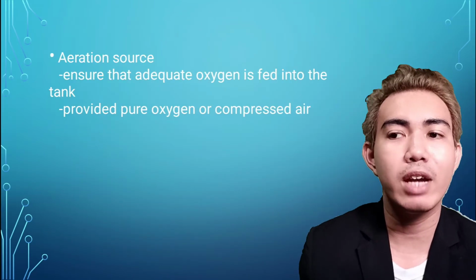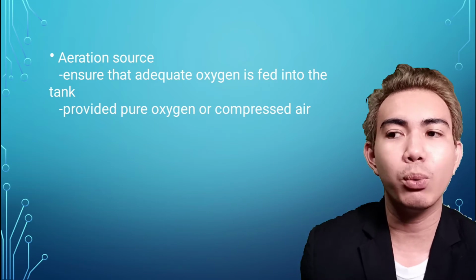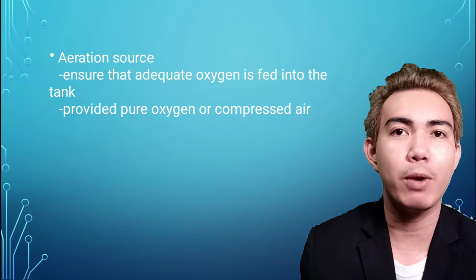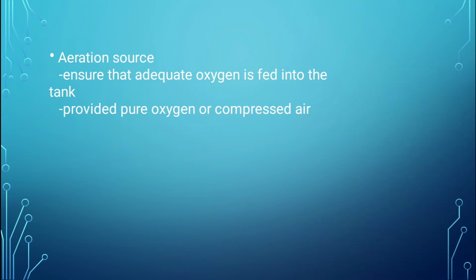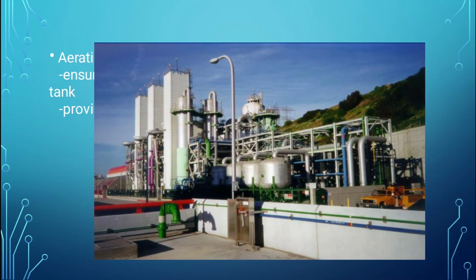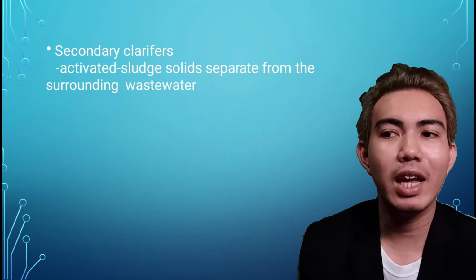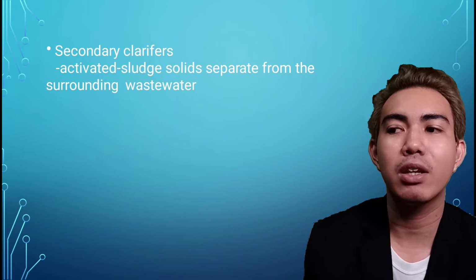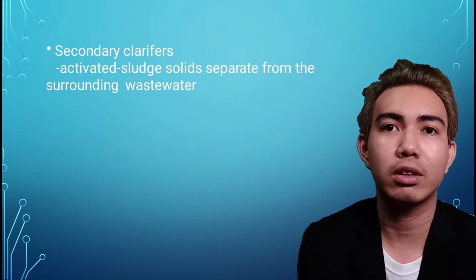Second, we have the aeration source. Ensure that adequate oxygen is fed into the tank. Provide pure oxygen or compressed air. The secondary clarifiers: activated sludge solids separate from the surrounding wastewater.